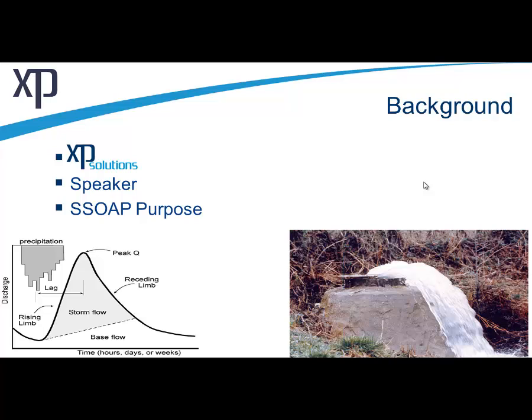The purpose of that is really to characterize what happens with a wet weather event. So when there is rain in the system, the sanitary sewer system is not leak proof by any stretch. So that rain will enter the system to some extent. It may enter it in a very quick way through an illegal connection or through some structural failures, perhaps in a manhole. So you can have some very direct, quick inflow into the system.